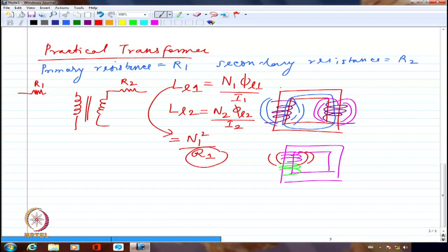If the reluctance in the iron core we are considering, the permeability keeps on changing depending upon at what portion of the magnetization characteristics we are operating the machine, right? So the permeability is not a constant in the case of a ferromagnetic core. So the inductance will not be a constant depending upon the magnetization characteristics portion where we are operating.